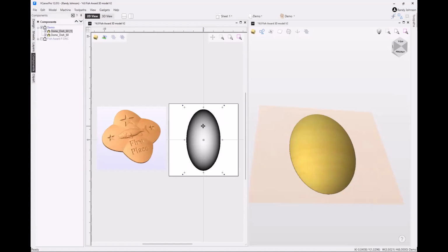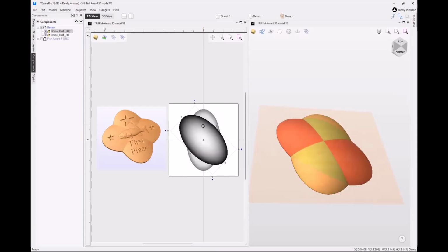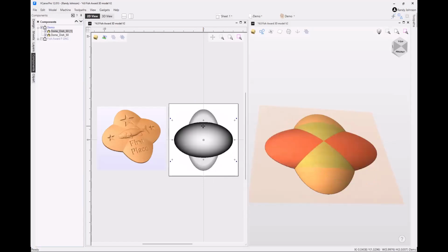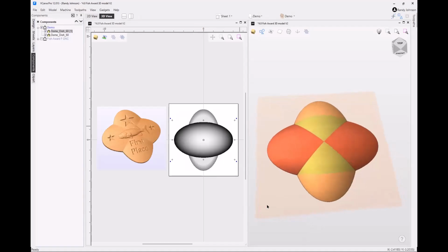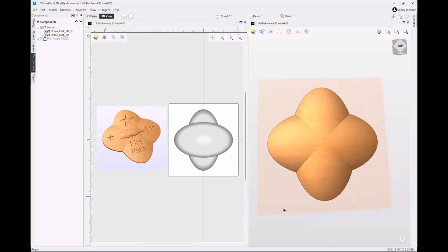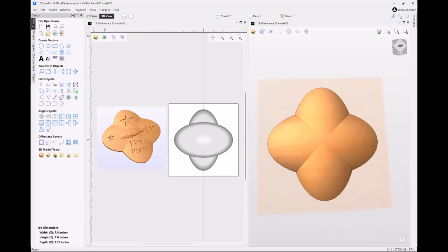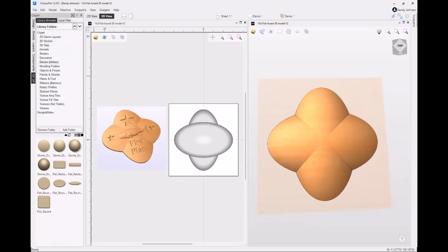Now here's a shortcut key that you'll want to learn. It's really handy. The 9 key or the 0 key will rotate these counterclockwise or clockwise. So I hit the 9 key and it rotates counterclockwise, 1 click, 2 clicks. Now you can see on the right side, since these are both set to merge, they are intersecting each other with that new shape. And so I've created this unique shape. And to that, then I can add the fish.